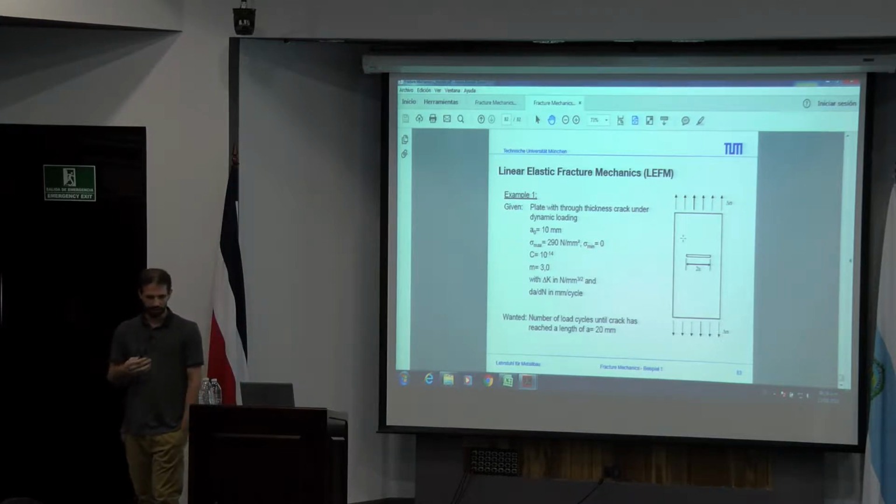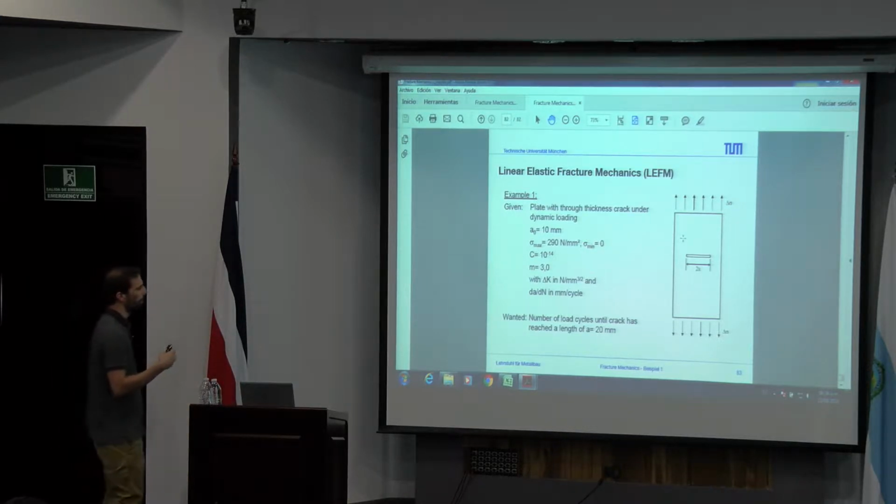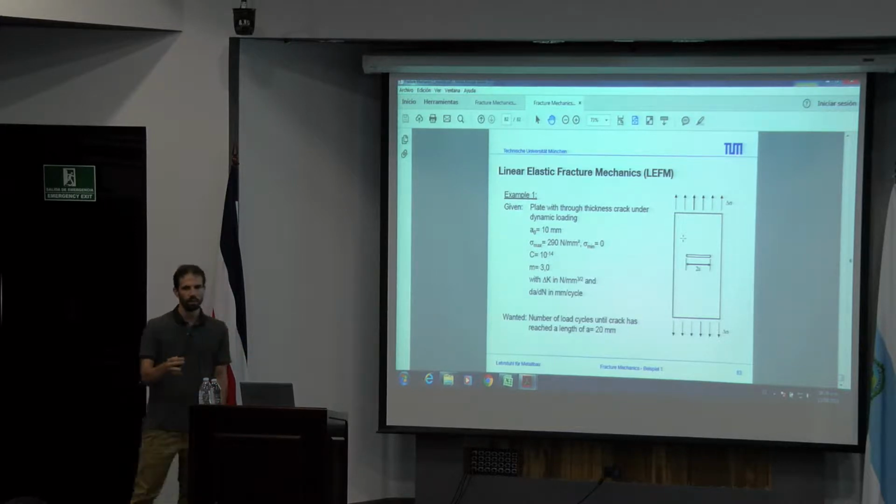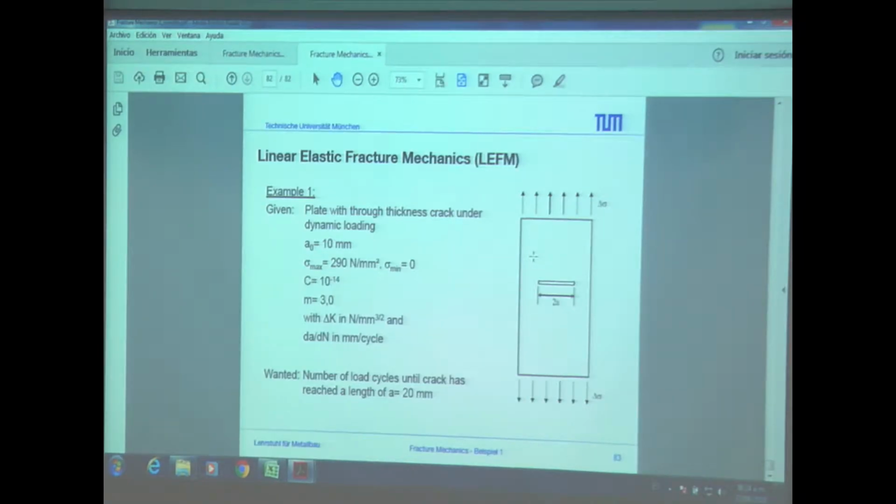Also last week I got a question: what is the difference between the fatigue design and the fracture design? Basically, the fatigue design always starts with no crack. So there is an ideal surface, you have no crack in your material, and this is basically the idea of the fatigue design. You start with the information of the stresses, of the stress ranges, and also of the stress concentration. This is how you decide on your resistance curves, and at the end you do your fatigue assessment.